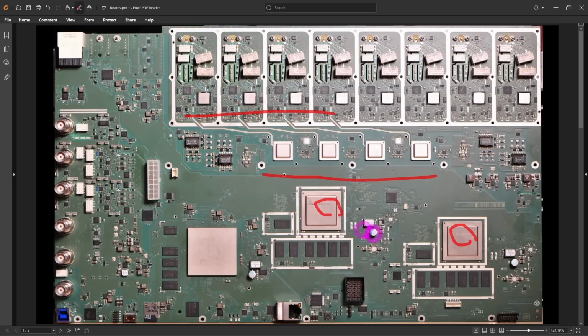Now on top of that, because you do have this 18-bit architecture with the Fourier transform that you have built in, you still get the really fast FFT, up to 45,000 FFTs per second, even if you're in the high definition mode. We'll see some of that as we're playing around with the unit. So it's not an easy front end, especially because you have to also get the memory and everything has to be interacting with each other. Now keep in mind that we do have this digital triggering architecture and some fancy digital functions in there, which I will show you. It also means that as you reduce the sample rate, you're still capturing those edges at the full rate because you do need that triggering, and that has some interesting consequences in the digital decoding of the architecture of the oscilloscope. So a lot of thought has clearly gone into it.